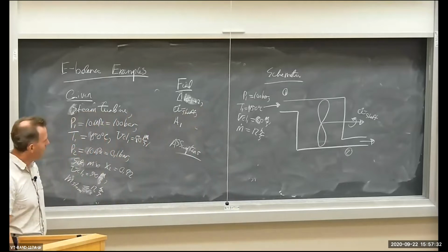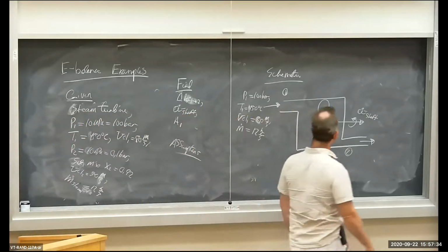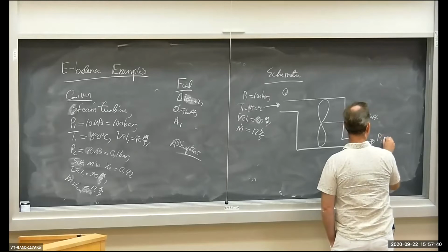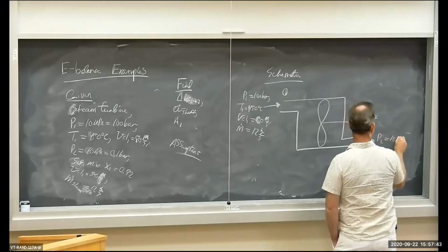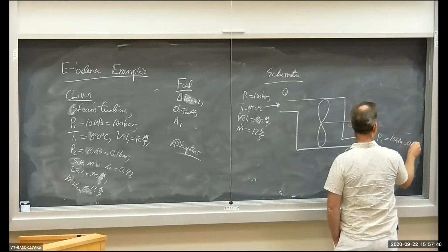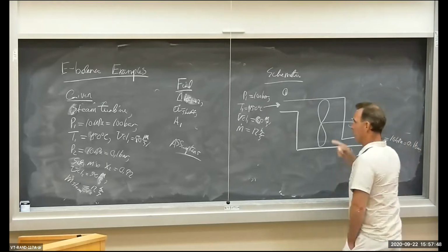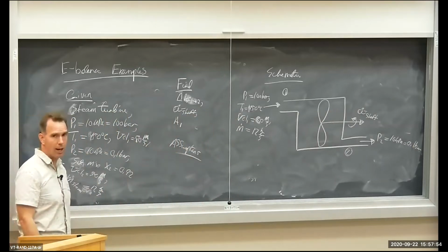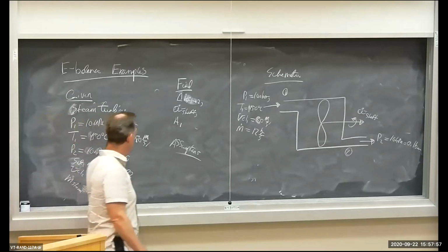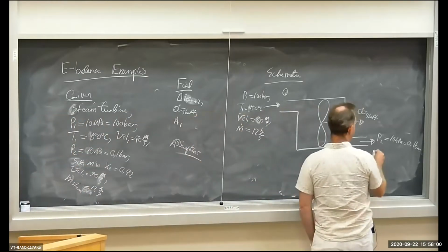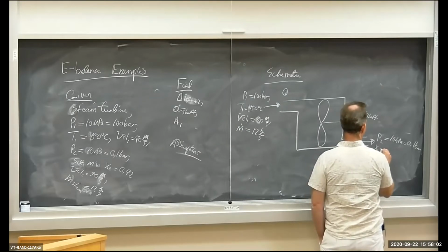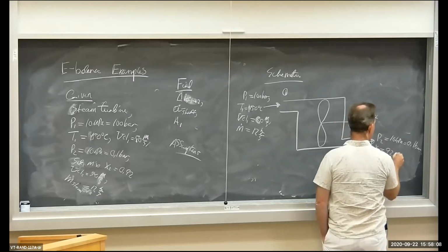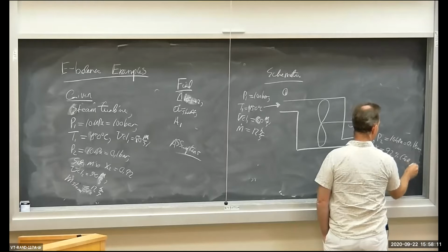the turbine. Now, the turbine extracts some energy from the flow, and as a result, our outlet pressure falls. P2 is down to 10 kilopascals, which is 0.1 bar. So pressure falls from 100 bar down to 0.1 bar. 1,000 times pressure has gone down. And we're also told that the exit state is a saturated mix. So we have a quality of 92%. So it's a saturated mix.